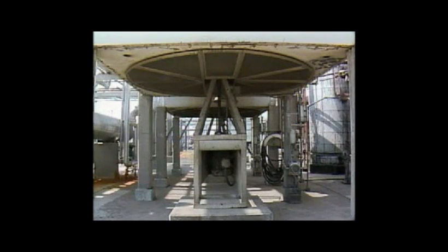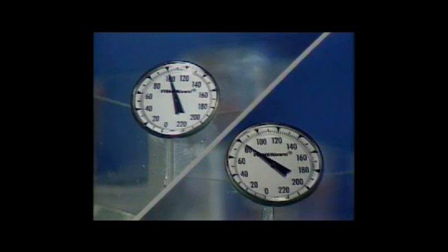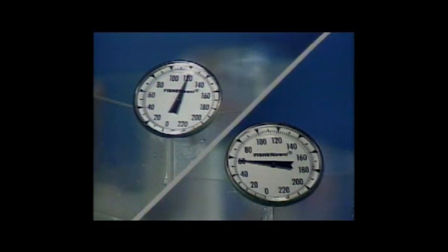During operation, the fluid being cooled passes through the tubes. The fluid transfers heat to the tubes by conduction and convection. Some of this heat is then transferred through the tubes and into the fins by conduction. From there, heat in the tubes and the fins is transferred by conduction and convection to the surrounding air. To increase the amount of heat transfer to the air, the fans in the cooler can be started. This increases the airflow through the cooler, which increases the amount of heat that is transferred by convection to the surrounding air. For example, as the difference in temperature between the two fluids in a heat exchanger increases, the amount of heat that can be transferred also increases.